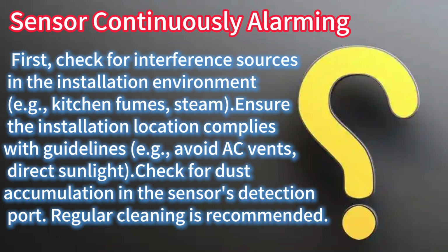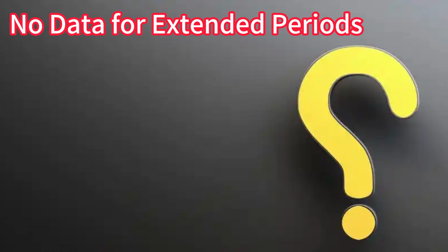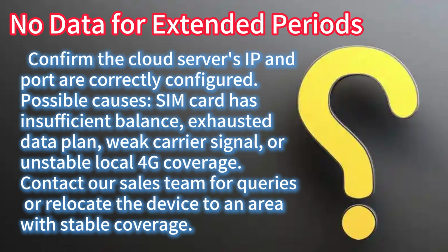Regular cleaning is recommended. No data for extended periods. Confirm the cloud server's IP and port are correctly configured. Possible causes: SIM card has insufficient balance, exhausted data plan, weak carrier signal, or unstable local 4G coverage. Contact our sales team for queries, or relocate the device to an area with stable coverage.